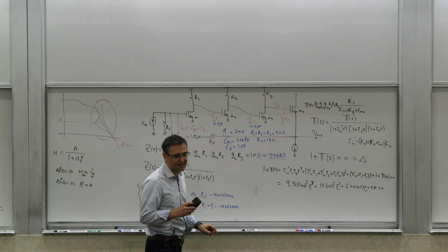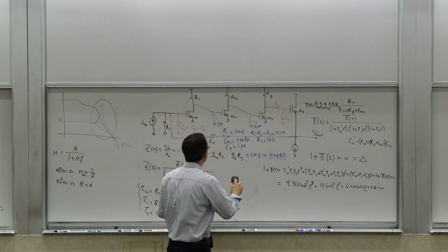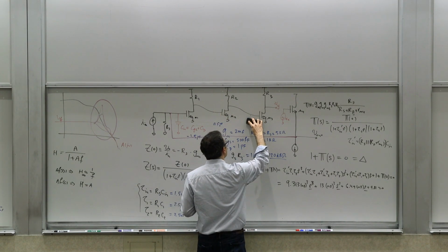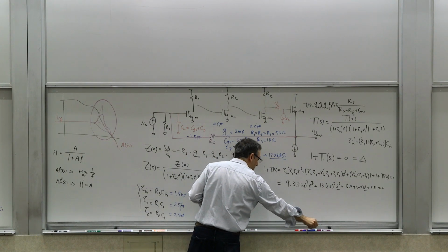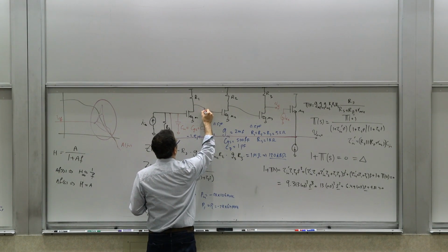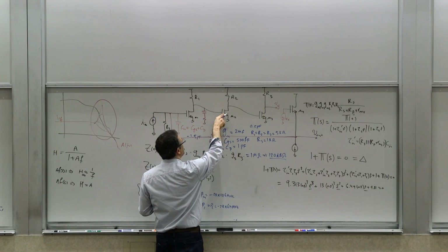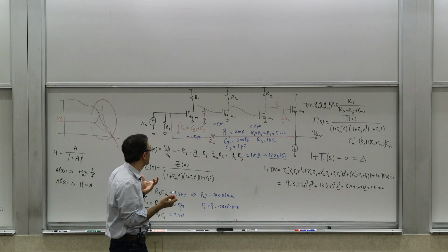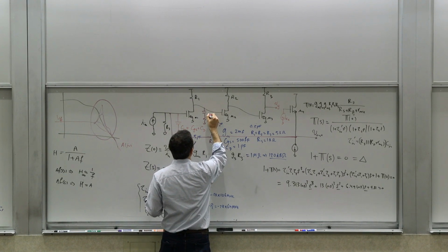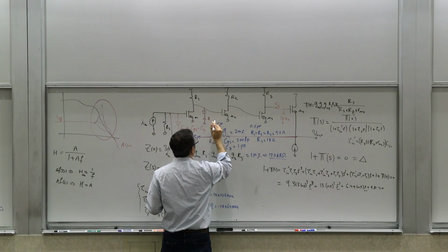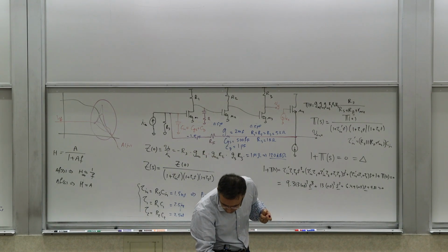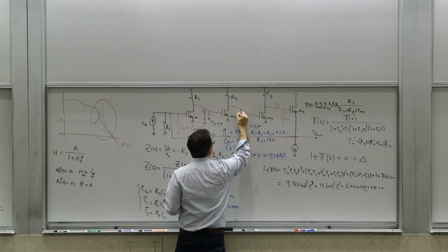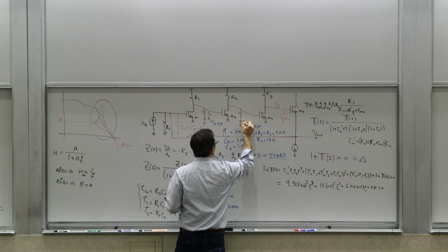The change we are making is that I'm assuming that these capacitors have some resistance in series with them. And this is not an unreasonable assumption at all. Because, for example, there can be series resistance for the gate, there can be channel resistance, things of that. So your gate can have resistances. So there's a resistance. Let's call it R1. We have used R1. What did we call them? Okay, RZ1 and C1 and C2, RZ2.